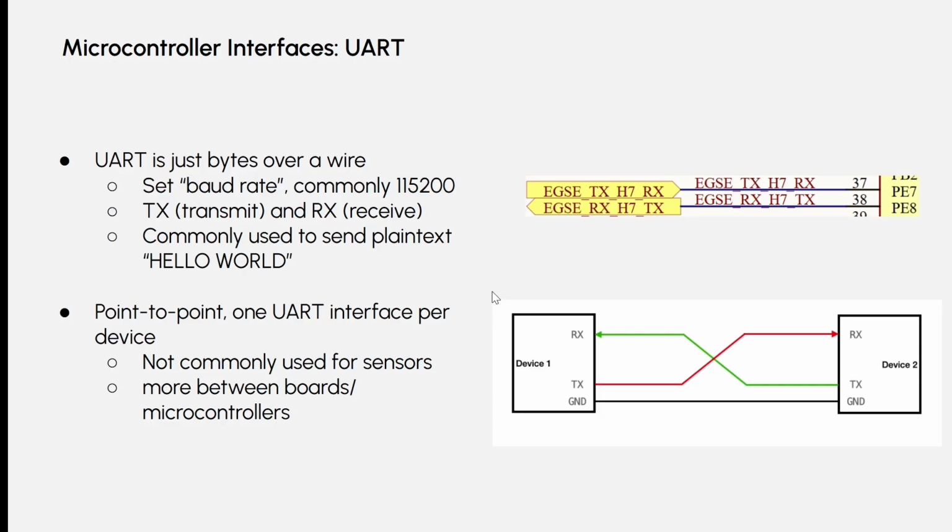That is one of the disadvantages. Unlike SPI or I2C, you don't have a bus where you can put 10 devices on it and you just have 2 pins on your microcontroller. If you want one UART interface going to one other point, it is point to point, you cannot share devices on the same bus. But it's good.